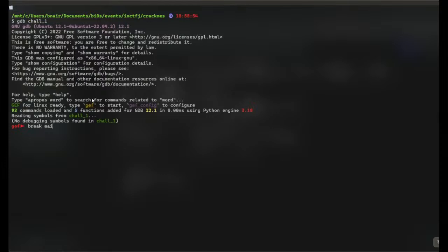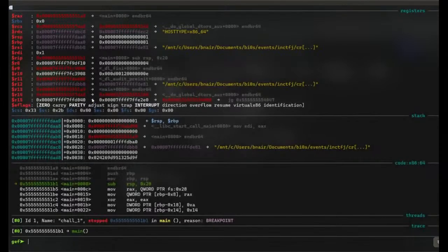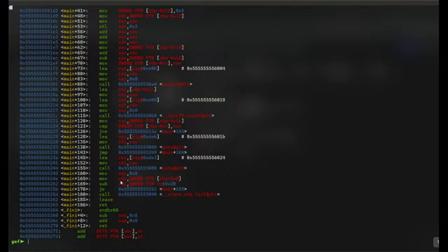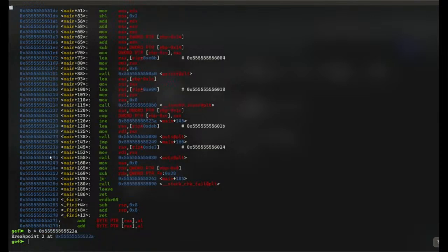Now I am running the program again. I just want to go to that particular address. Okay, let us see. We see one puts here. Basically, we wanted to go here, right? We take this address and I put a breakpoint there. A breakpoint means that whenever the CPU comes across that address which contains an instruction to execute, it will stop executing over there. So I'll be continuing.